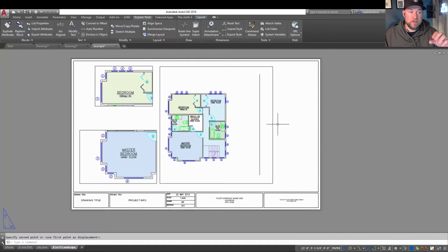This can also help you set up a specific or an odd scale by drawing a line in your Paperspace or a layout space that is a specific length or a dimension at a specific length. You can then match or align the objects within model space to match this Paperspace object.